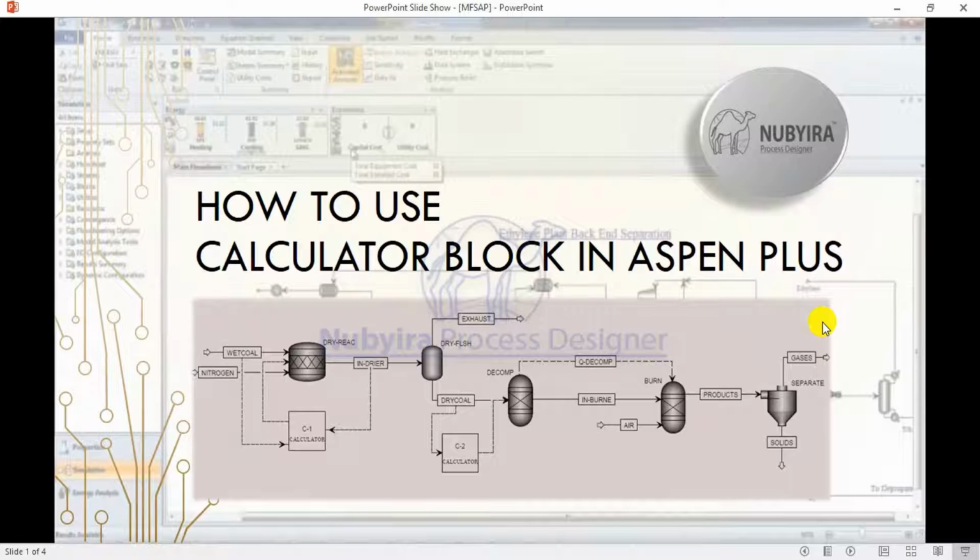It helps you to calculate your flowsheet and insert some calculation code or statements in your simulation compilation. Instead of using Fortran, you can even use an Excel flowsheet or Excel equation function, just a relationship between two cells. You can use it in your simulation through a calculator block.